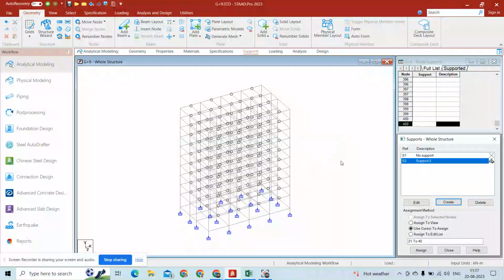So hello viewers. Today I came with part 2 of G plus 9 shopping mall design in CAD. As you have seen in part 1, I have started the modeling and up to this we have done. In today's video we will create the stair headroom. For stair headroom, usually we provide a minimum of 2.5 meter height, and in our case we will provide 2.5 meters.